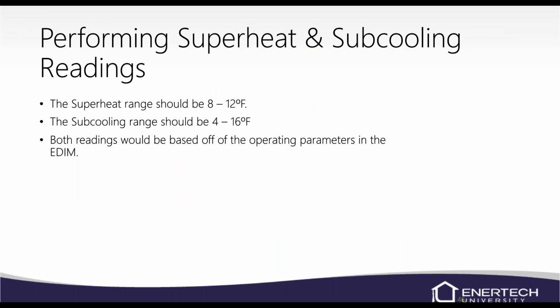Superheat range is usually about 8 to 12. That's why I say the 10 number is a good number to remember. And subcooling is somewhere between 4 and 16 normally. So again, 10 falls right into the middle of that.